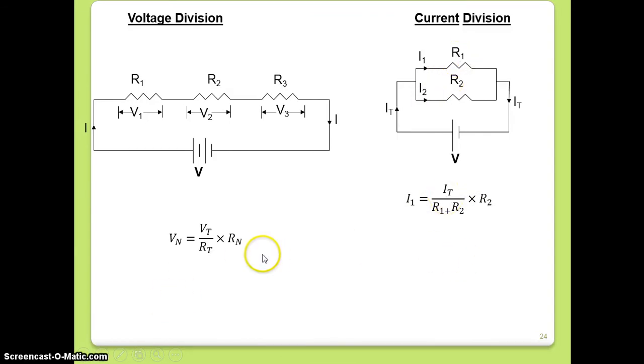I hope you note down these major differences. In voltage division, we take the same resistance, but in current division, we have to take the opposite branch resistance. In other way, voltage division can be applied to as many resistors that are connected in series, but the current division we normally apply to only a network of 2 resistors connected in parallel. If you have more resistors connected in parallel, then you need to make a small modification or a rearrangement to the network so that finally it looks like only two resistors.